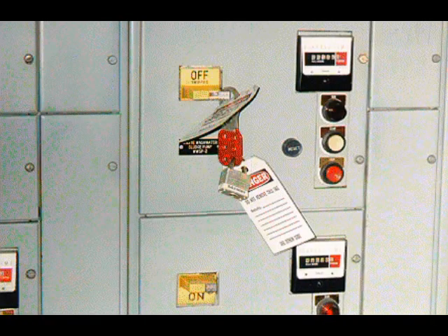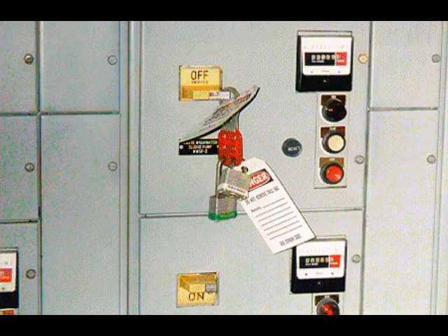You know that the electrician has already locked out the power to the unit because he is installing an ammeter. You are planning to change the impeller on that same pump. What is the first thing you should do? You must put your lock on the motor control center or breaker that provides power for the motor. This means that the lockout will have two locks on it, yours and that of the electrician.